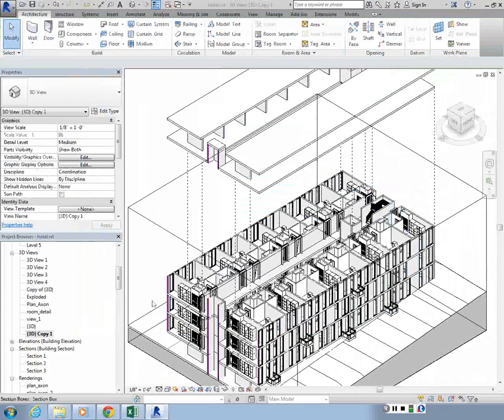So work on something like this using the displacement sets. Again, you can do one for the overall project and one for individual units to show how they're located, or where they're located in the project. For your individual units, you can also use this diagram, right? So I asked you to hide the sidewalls. You can also create displacement sets for those as well. So you can move one side of the room away from the model and the other side as well, and add the displacement lines as exploded, and just take a hidden line image of the axon.